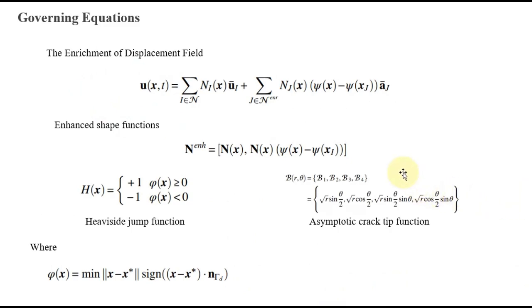In order to model the discontinuity or crack interface in the XFEM, the nodal points of elements cut by the discontinuity are enhanced using the enrichment function psi(x). The enrichment of the displacement field, you can see in this shape. The N(x) denotes the standard shape function.